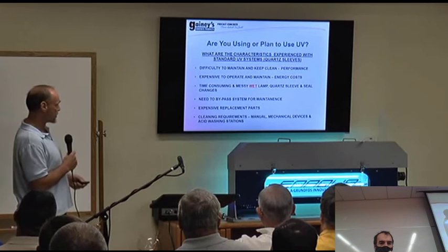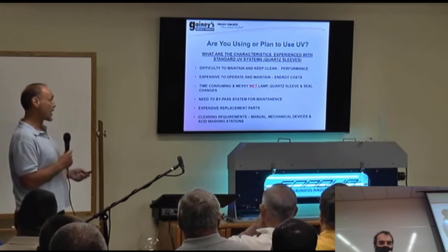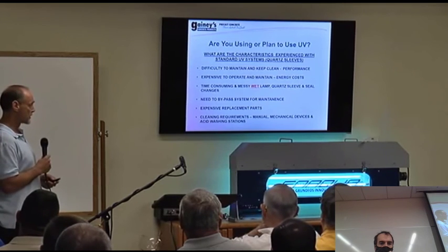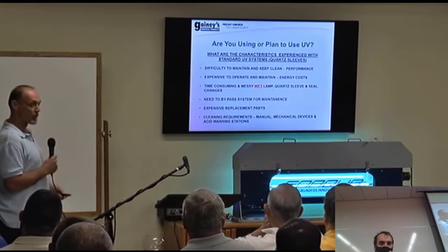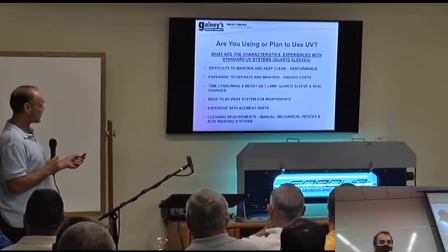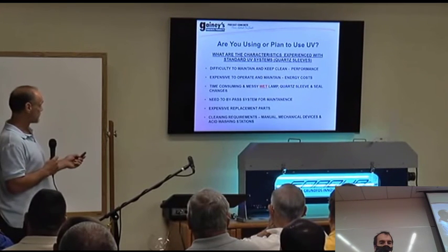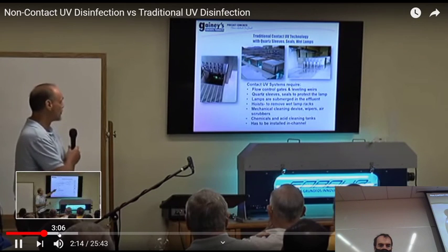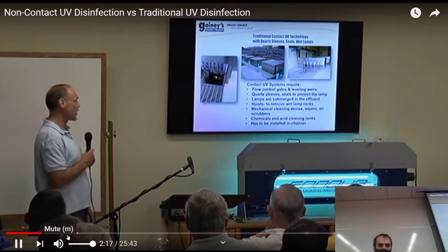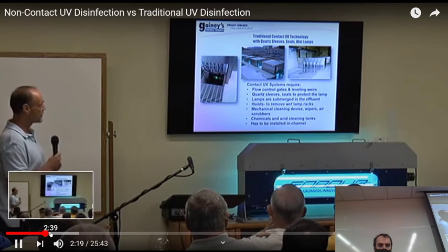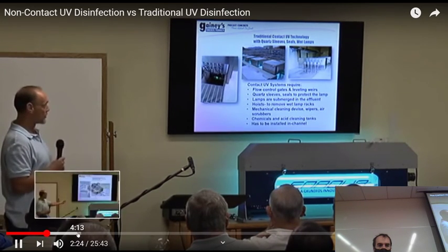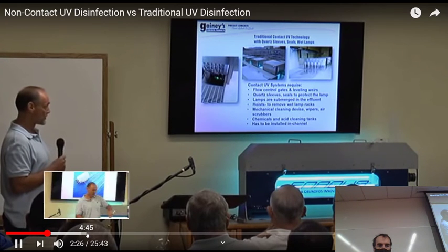And cleaning requirements. Quartz-based systems can have manual cleaning, mechanical devices, either pneumatically driven. So it shows an example. So contact UV requires gates upstream and leveling weirs downstream, making more expensive installation, bigger footprint, more civil work. You have quartz sleeves and seals to replace.